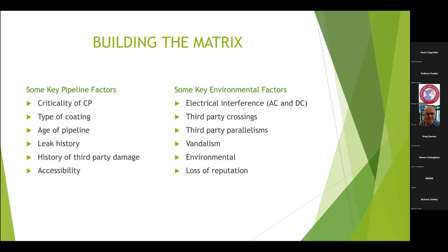If you get some other electricity on it that you don't want, that can affect what's happening to the cathodic protection. And the kind of things that create a problem are overhead power lines for AC and DC these days, buried power lines, AC and DC, AC railways, DC trams, mining activities, DC from workshops where they're doing a lot of welding, that kind of stuff.